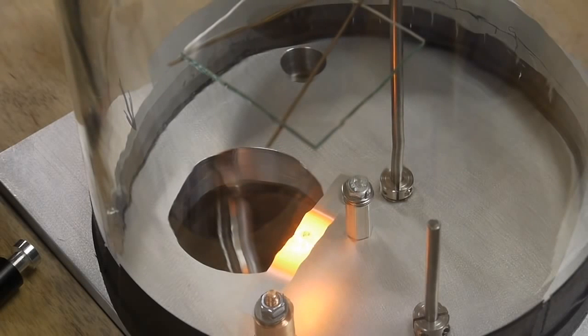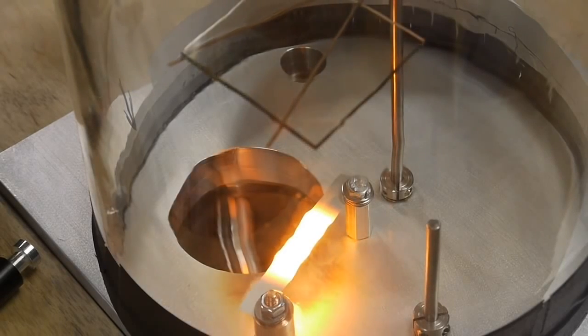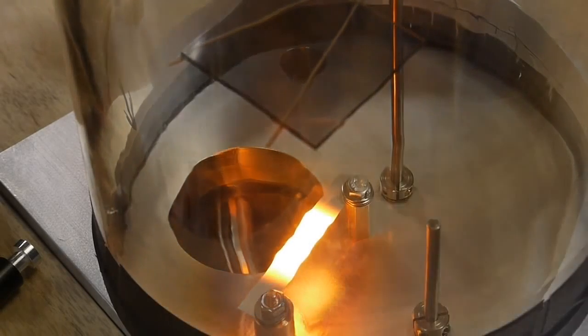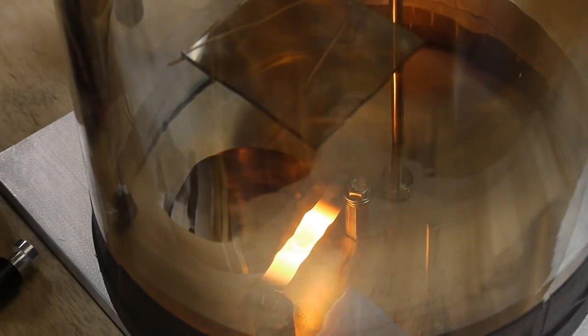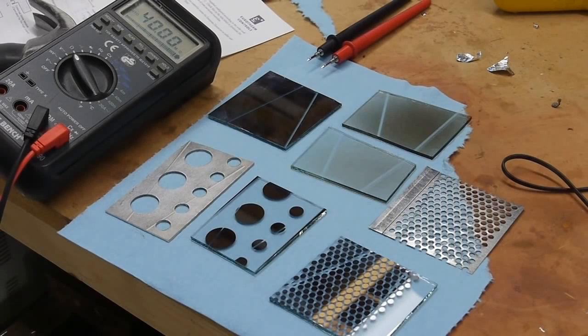This process occurs in a vacuum in order to minimize collisions between the source particles and any background gas, as these collisions can result in reactions, which decreases the amount of source that reaches the substrate, which would make thickness difficult to control. Uniformity can sometimes be difficult to control due to the fact that the source particles are deposited from one direction only.